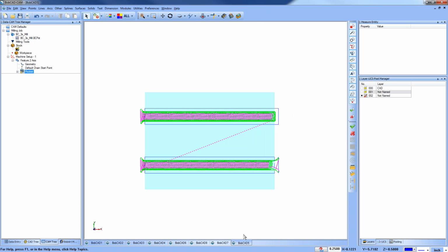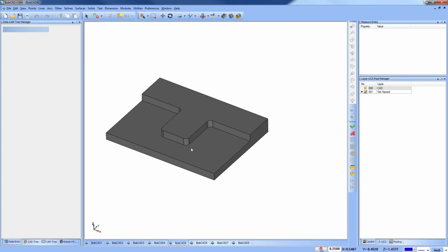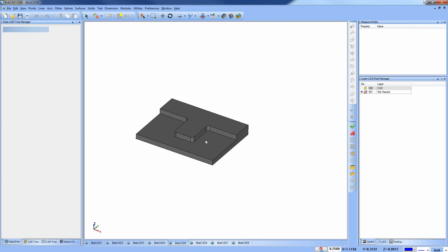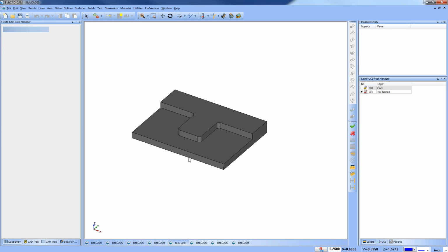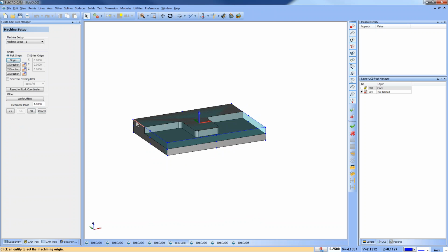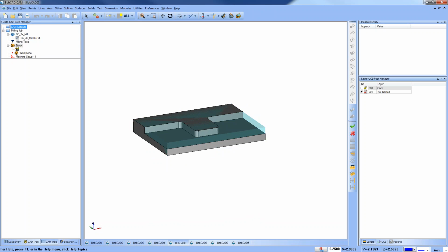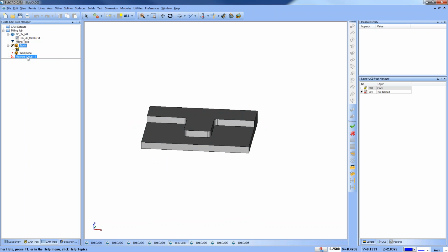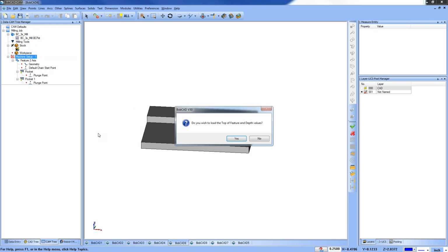Okay. So this is a two-sided open pocket. Let's go to number 6. This is a three-sided open pocket. So again, we're going to have the same procedure for open pocketing. We're going to load up our new job here. We'll set our 0 position. So we'll set our origin back here. All right, I'm going to blank out my stock. I'm going to paste my machining feature.